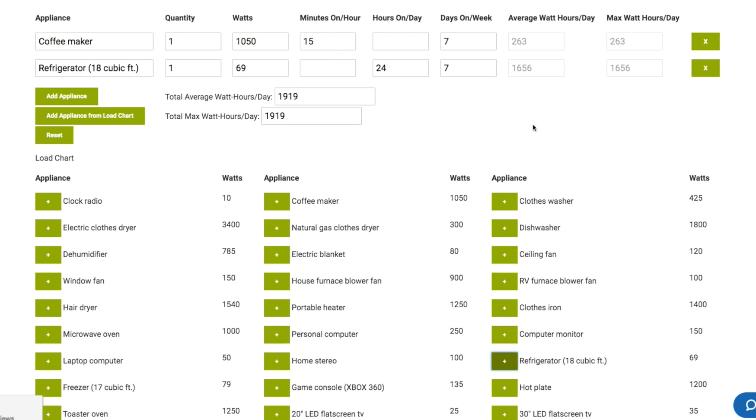So this refrigerator value has been adjusted to a 24-hour period of time because it has a duty cycle. Your average refrigerator usually draws about 1.5 kilowatt hours a day, or 1,500 watt hours a day. Now that'll vary significantly. If you get a brand new Samsung or LG refrigerator that's just come off the market with inverter-based technology inside it, those things are extremely energy efficient, and you might cut that value in half.